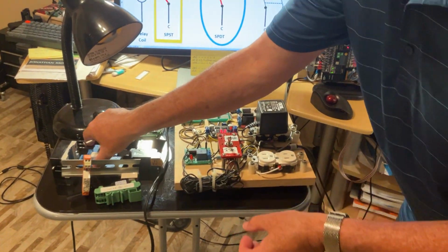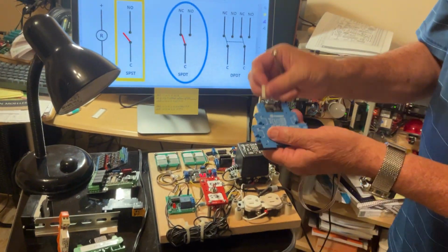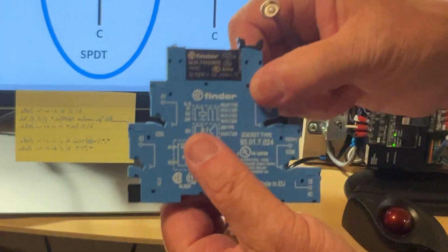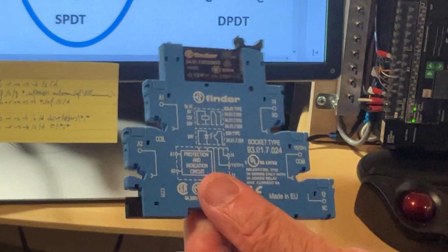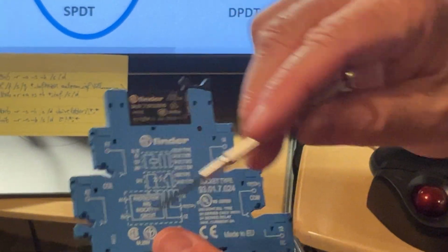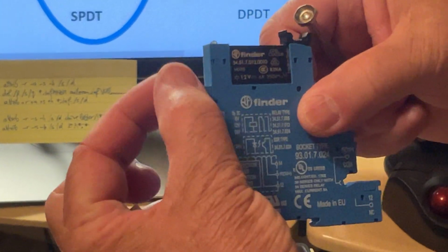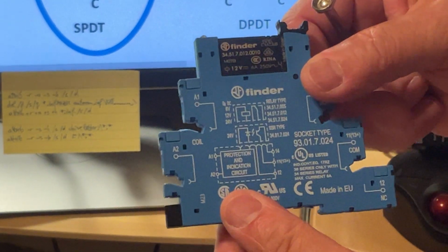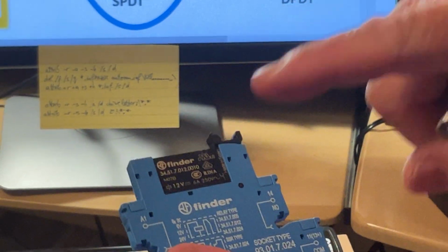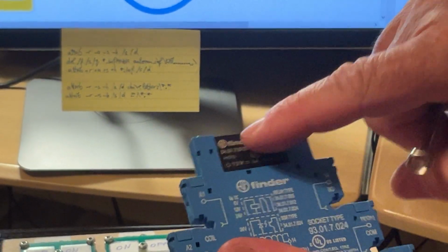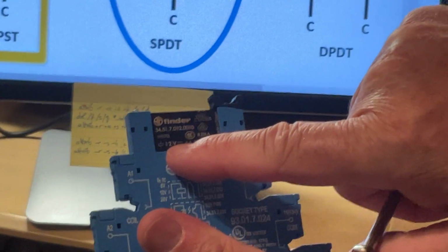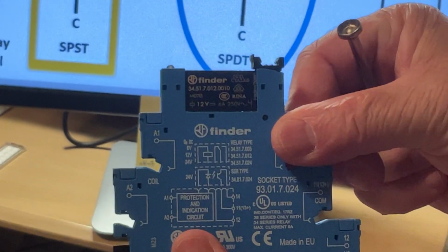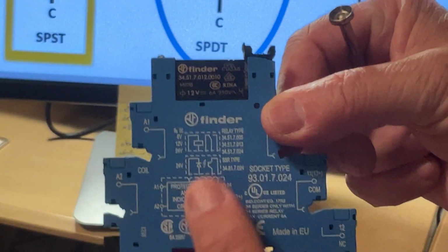And the third one I'm showing you is this one. It's made by the company Finder. And the big blue body here is only to give you contacts. They even show you on the blue body the wiring arrangement. You have access to screws everywhere, but the actual electromagnetic relay, it's not a solid state, it's an electromagnetic relay, is right here on the top. The coil is made for 12 volts. So this one is for 12 volts, but I can order another one for 24 if I want, okay?